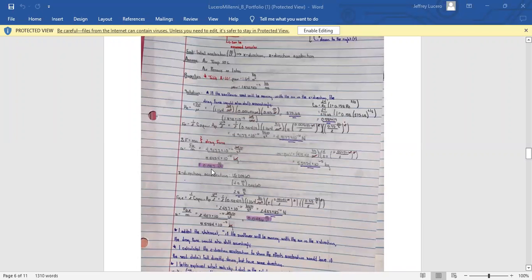Okay, this makes sense because it's a small volume, which means there's a small surface where the air can grab the seed to get a small velocity in the x direction. So we already know that the z direction acceleration is at a 60-degree angle, so we can calculate the velocity with 4.5 meters per second times cosine 60 to get 2.5 meters per second. For the drag force, it's the same idea as the x direction, just for the z direction velocity, to get 2.437 times 10 to the negative 6 newtons, or kilograms meters per second squared. Then we can find that acceleration to be 0.0436 meters per second squared because we already know the mass and we found the drag force.